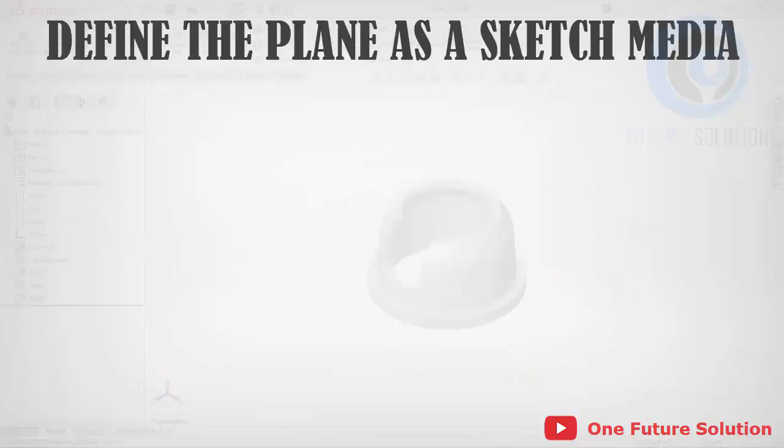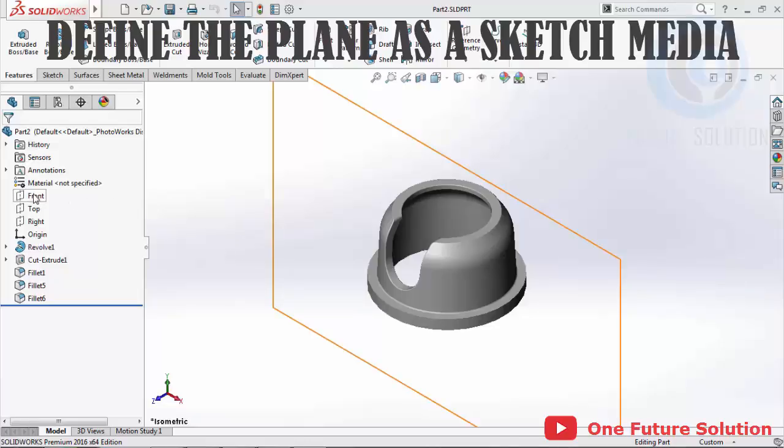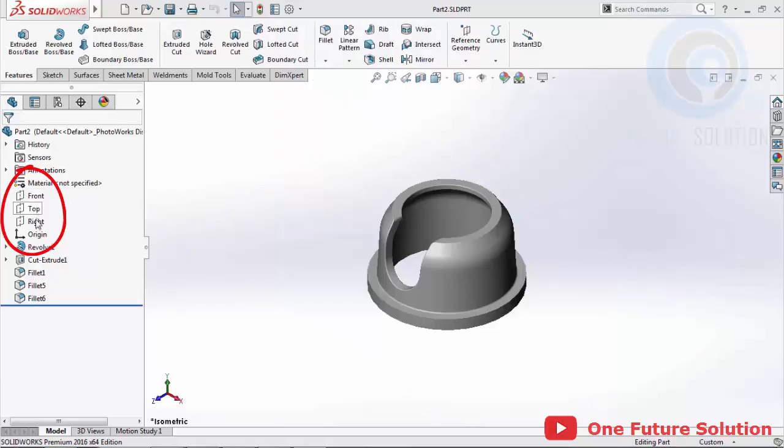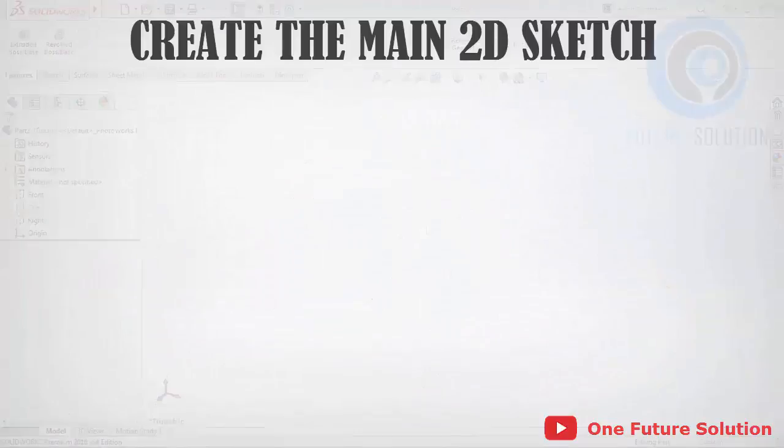3. Define the plane as the sketch media. If we want the 3D model placed like this picture in SolidWorks, we should choose the plane that we will use to place our 2D main sketch profile. Look at these 3 main planes. Because we will use the Revolved Feature to create the 3D model geometry, we can place the main sketch profile in the front plane or right plane. We shouldn't choose the top plane, because this plane is not suitable in this case to create the model as we want.